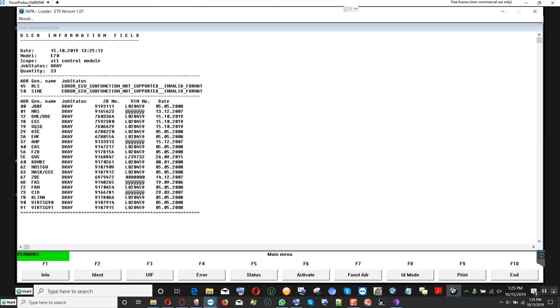There goes the VTG. VIN number changing. You see that? The DME, the VIN number is changing. And the EGS, the VIN number is changed. Yes! I did it! I changed the VIN number of the DME and the EGS with WinKFP. I did it, man. And now DME, EGS, VSG has the VIN number changed.